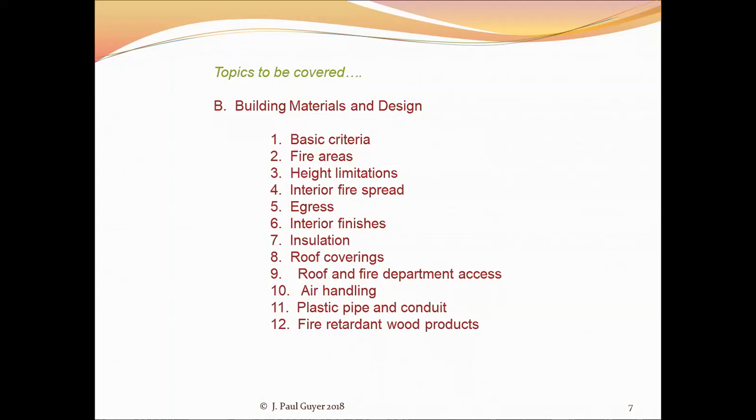As far as vertical access is concerned, usually this is a stairwell, which is constructed of a highly fire-resistant type of material, like poured in place concrete or concrete masonry or CMU blocks, something like that, so that the stairwell's structural integrity is maintained all of the time that the fire is being fought.